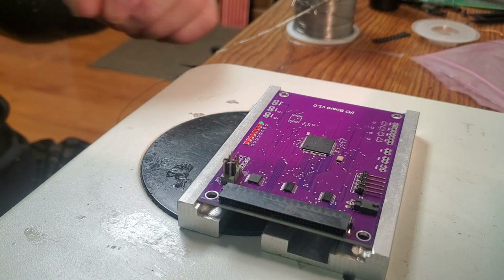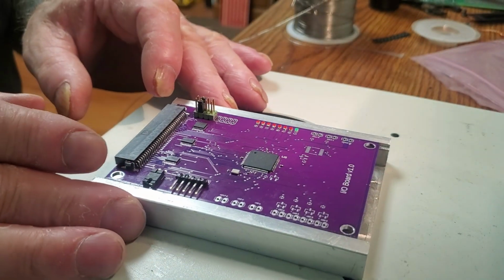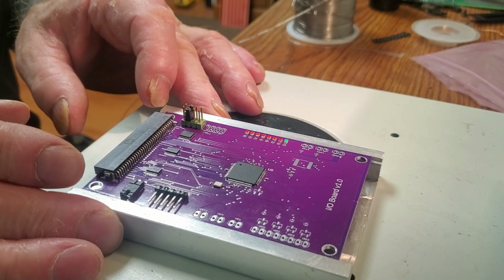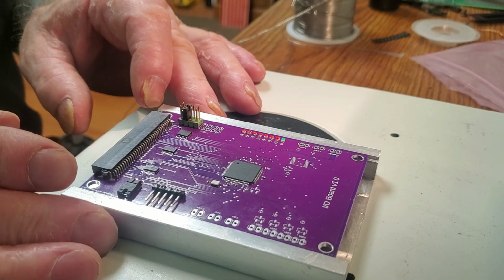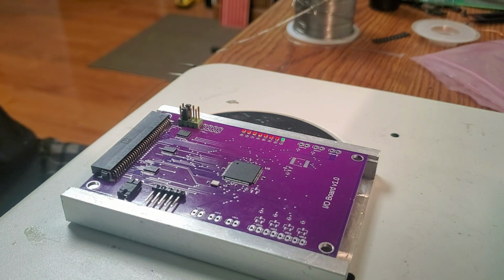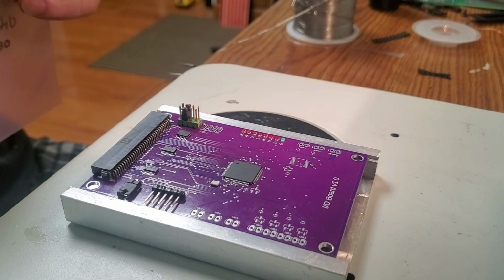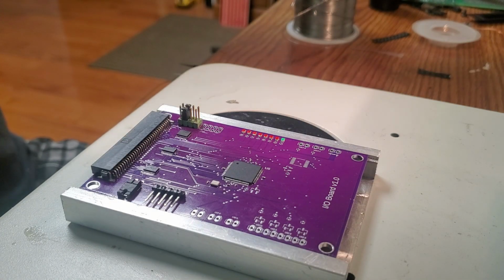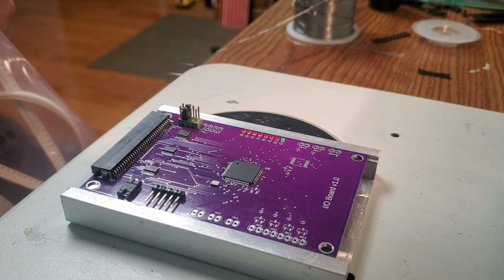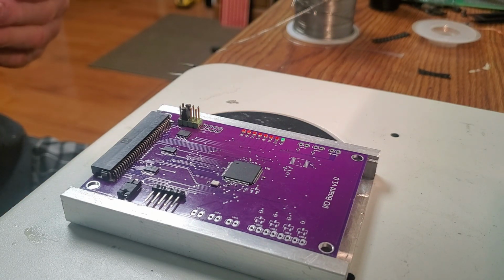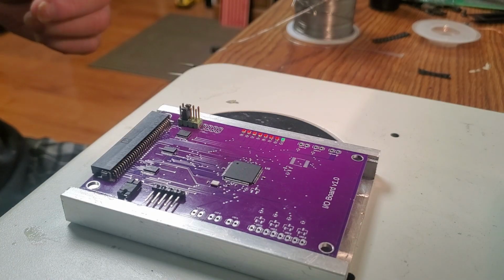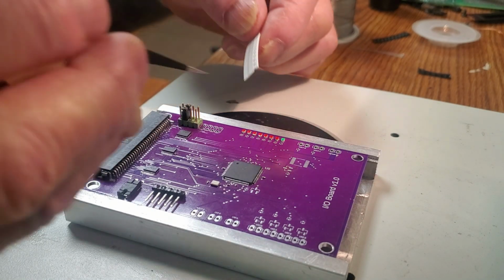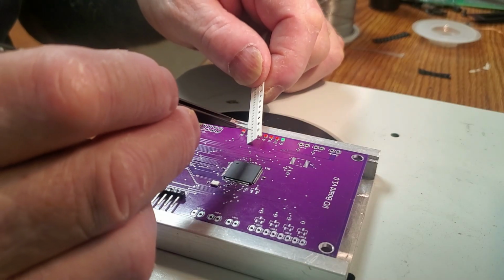Okay, there's the beginning. Now let's do the resistors. The resistors, I was at one time earlier on using 1K, and you get a pretty bright LED, but to reduce a little bit of power consumption, I moved to a 1.5K. So I haven't 100% decided to stick with that yet, but it seems to be working okay. But we'll see how it works later. And maybe we'll change it on the next boards.